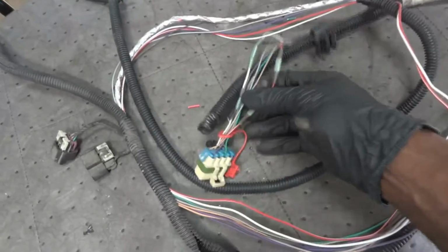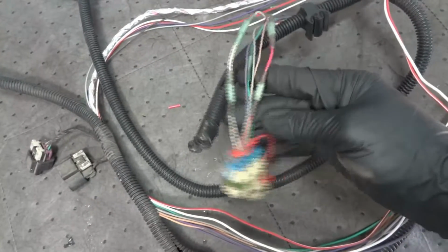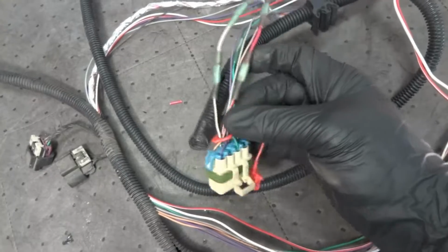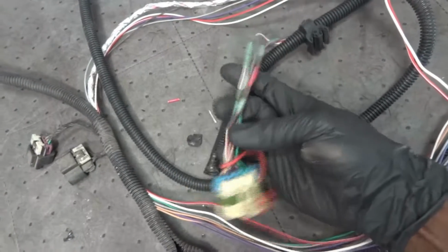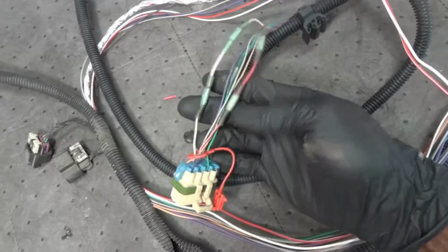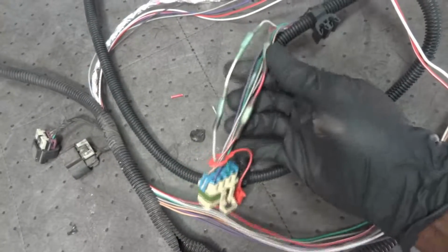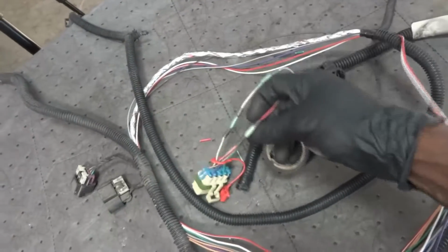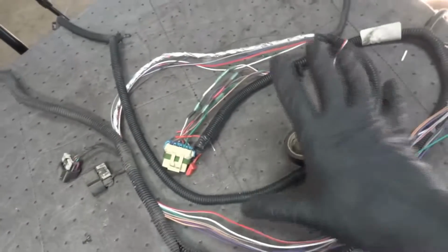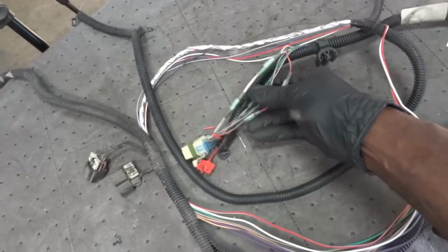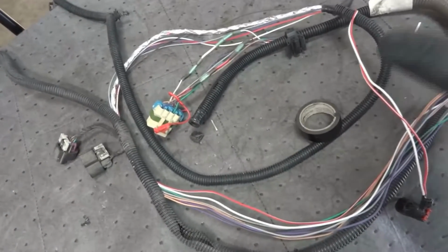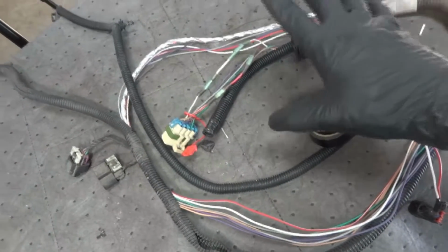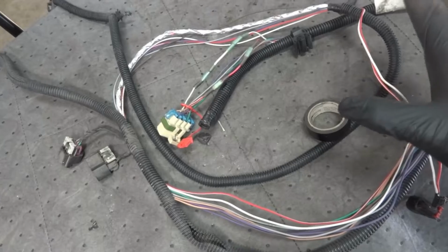All right, so I want to show you the wiring repair that I did. So I used these shrink butt connectors to fix the wiring. So these shrink butt connectors are really good. They seal the wire very well. So now I'm going to tape all these wires up and put the wiring back in the wire loom, and after that I'm gonna reuse the old vent solenoid. I'm gonna reinstall the old vent solenoid, and then I'm gonna put the fuel tank back together.